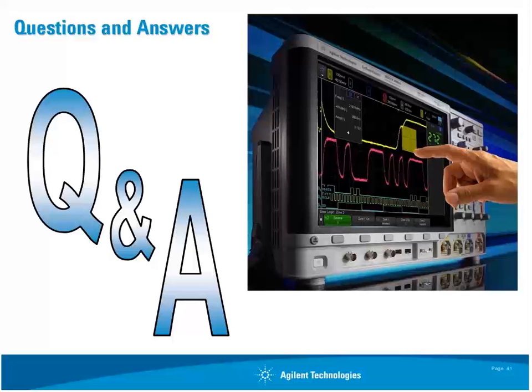Okay, I did show one example of the scope updating at 1,000 waveforms per second, and another example updating at its maximum rate for that particular setup condition. The way I did it in that example is that most scopes on the market today have what's called a trigger hold-off capability. The primary purpose of trigger hold-off is to trigger on a burst of signal, so the scope can sync in on, say, the first pulse of a burst and not randomly trigger on the second, third, fourth, 100th, whatever.